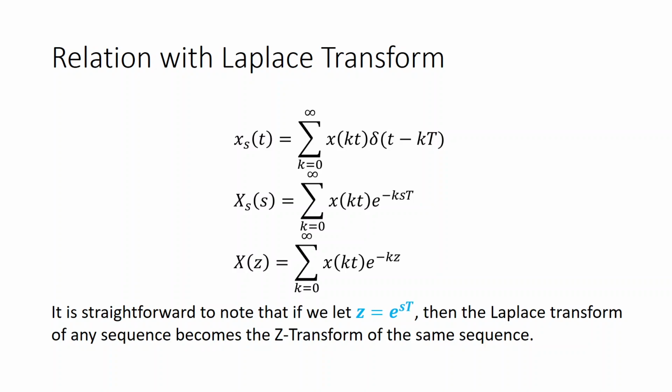This is the vital information about discrete time systems in frequency domain with the help of the Z transform: the relationship of the Z transform with the s transform, the stability criterion of poles being within the unit circle, how you can break down the signal as a power series as well as a sum of partial fractions, then the idea of discretization, digitization, sample and hold.